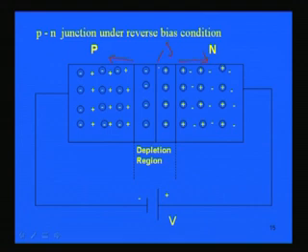As a result of that, more and more uncovering of the fixed or bound charges will take place, because these carriers will move away, they will be surfaced out. As a result of this, the depletion layer, depletion region will now be extending, it will be increased.